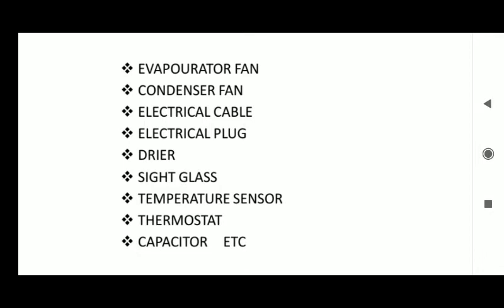So when a condenser fan shuts down or goes bad, the compressor gets overheated, and if it's overheated, it shuts down the AC. This has happened in various companies. We have experienced people whose condenser fans were not working, and the compressor shut down. If you have a good system that is protective enough, your compressor will protect itself by not getting burnt. But if your compressor is not well protected, I tell you, as the fan is not working, if it gets overheated, your compressor can burn down. And the compressor is the most expensive component in an air conditioning system, so you need to protect it.